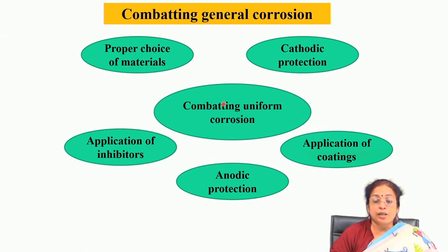You can as well apply a very thin coating made of a more active material, like zinc coating on steel. When zinc coating is applied on the steel, initially it acts as a barrier coating, and gradually, when the zinc gets corroded or damaged, in that case also it protects the surface by the process of sacrificial action. So, you call it cathodic protection.